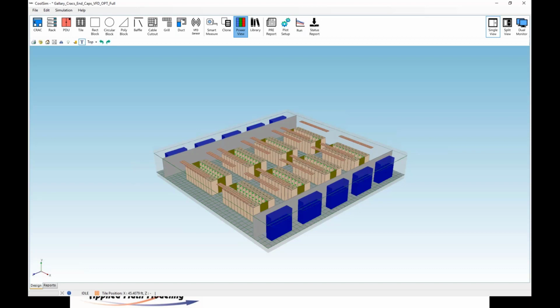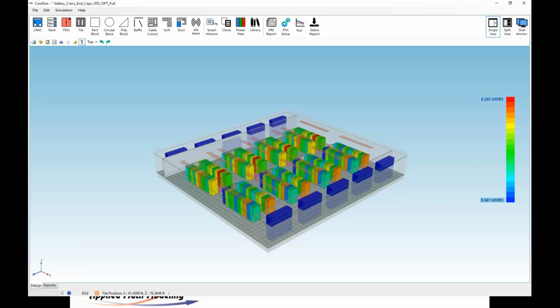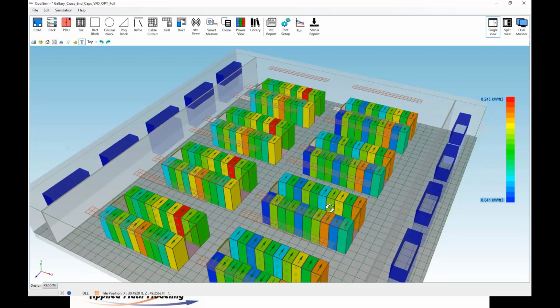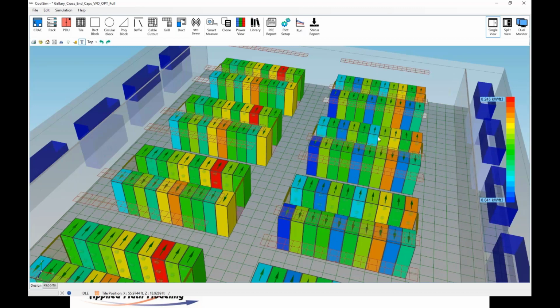So what you have to do is use good engineering judgment to try to steer things in a direction that is going to be good for the customer and good for the prognosis of the data center over time. So in this case, what I did, instead of loading those uniformly, is I loaded them in a particular way that varied the load across those racks. And here's a plot of how I loaded them. This is a load plot here. It's called Power View that we have, and you see here that in some areas I'm more heavy than others, and I tried to uniformly distribute the load around the room.